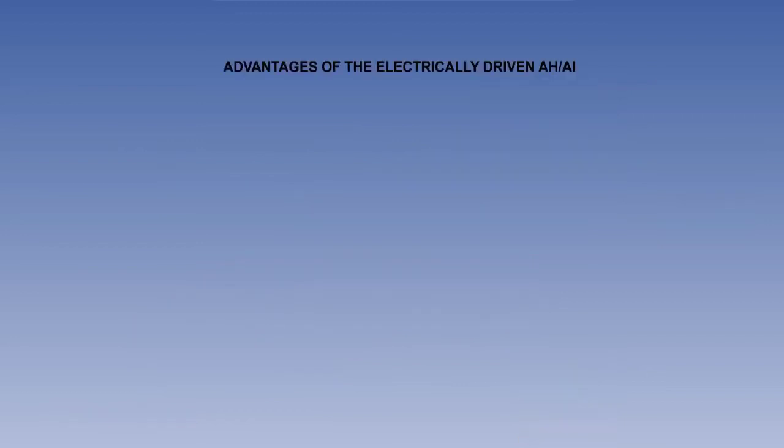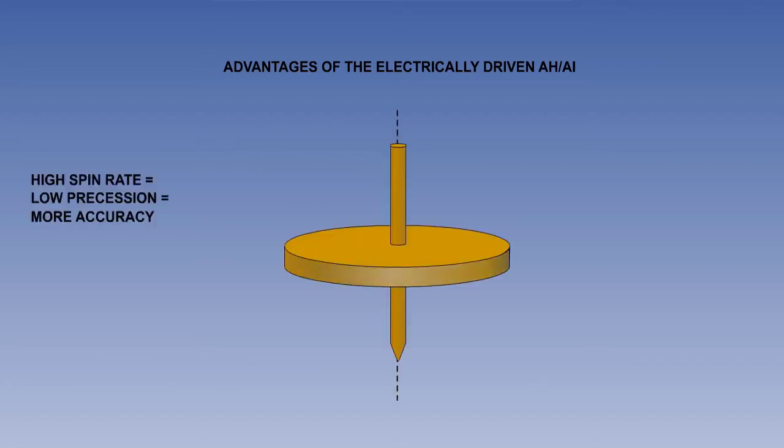Advantages of the electrically driven artificial horizon, or attitude indicator, over the air-driven instrument are: firstly, there is greater rigidity, due to the higher spin rate possible, which in turn will give a low precession rate. There is less potential, therefore, for the gyro to move out of Earth vertical, and so more accuracy can be achieved.